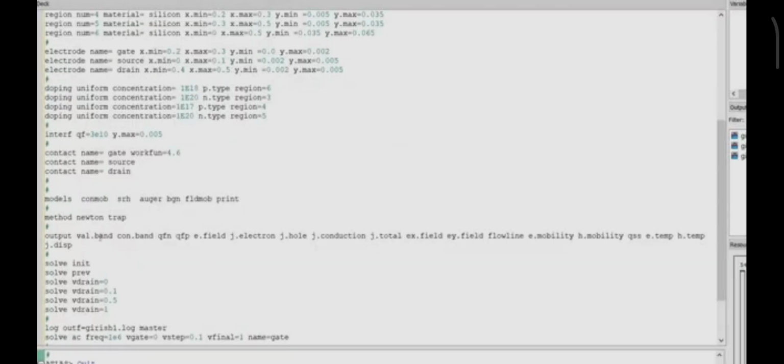A structure file or solution file provides an image of the device at a particular bias point, DC simulation or transient solution point. This .str file should be plotted using TonyPlot. Several quantities are saved by default within a structure file, for example doping, electron and hole concentration, potential, and electric field. To save these files, the following command would be used.